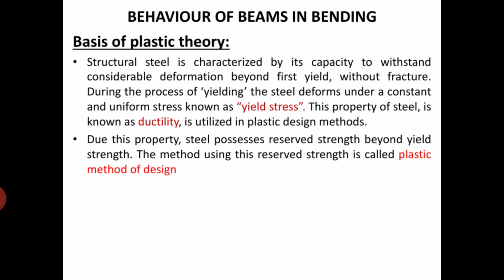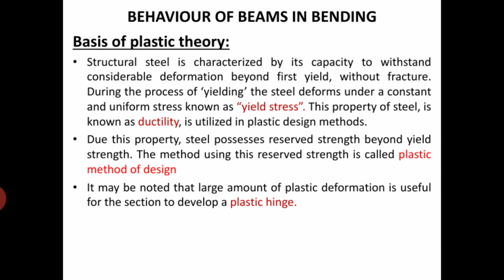So this method leads to economy in design, and in plastic analysis we use an idealized stress strain curve. It may be noted that a large amount of plastic deformation is useful for the section to develop a plastic hinge. How the plastic hinge forms, and what the nature of the plastic hinge is, we'll discuss next.